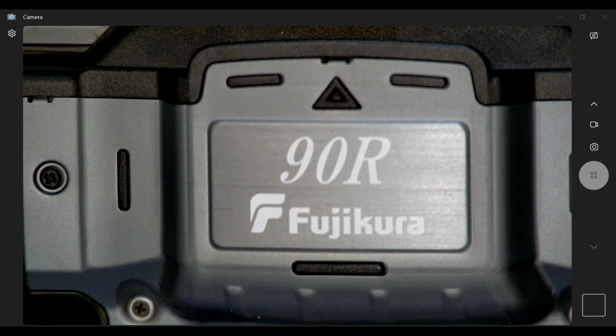Anything to add, Craig? Mega's correct. The main thing with arc calibration is you have to do this almost on a daily basis due to the barometric pressure changes. When you have a high pressure system roll into town, it will actually compress the oxygen molecules. You will have more oxygen present. As a result, your arc will burn hotter. So it's why we recommend daily arc calibrations.